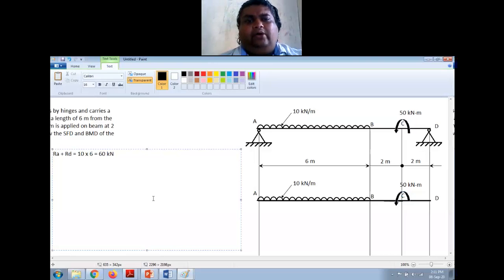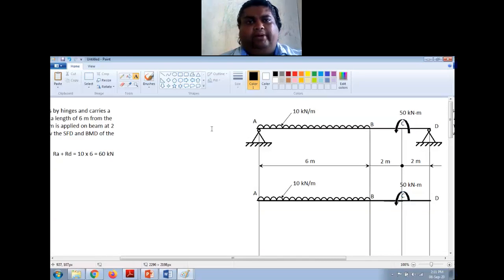Okay. Now I have to take bending moment at A or D. Either end I can take, and I have to find one of the reactions, so that I can find the other reaction. Now the usual convention is I'll take bending moment at A. For doing that, I need the sign convention for bending moment. So we will do the exercise we always do in our numericals. Draw a box like this.